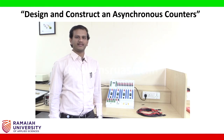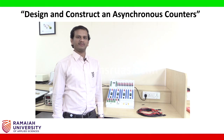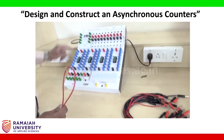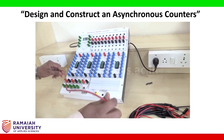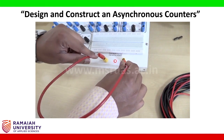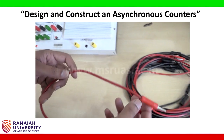Before connecting the logic diagram, let us check the continuity of the patch cords by placing each patch cord into the continuity tester. So turn on the power supply of the digital IC trainer kit. The LED bulb is on, the power supply is on now. So now we have to place each patch cord into the continuity tester. There is a beep noise and LED is on, that means this patch cord is working. So this test is performed for all the remaining patch cords in a similar way.